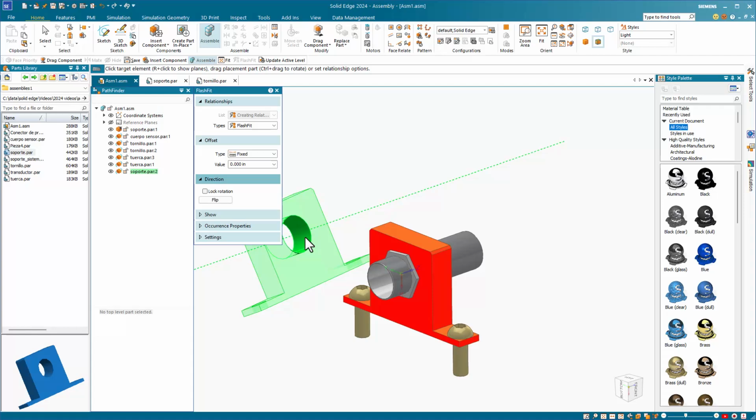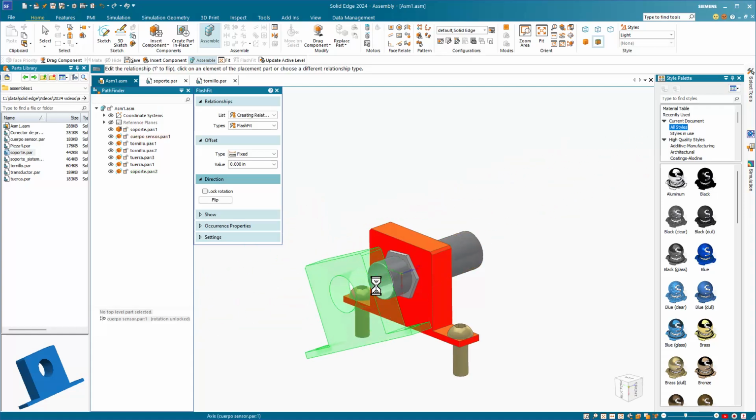Click on the inside face of the part that you want to move first, and then the reference part. It doesn't always work out the way you specify, but when there's an open degree of freedom, it will. For example, if one of the parts is grounded or mated to other parts, it may not move as you expect it to. But when the open degrees of freedom allow it, the first part you select moves, and the second stays stationary.